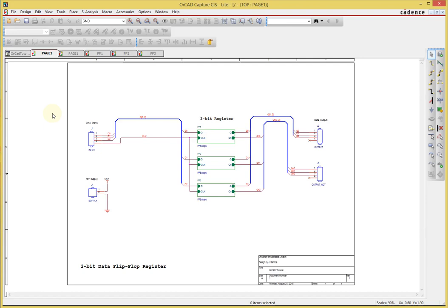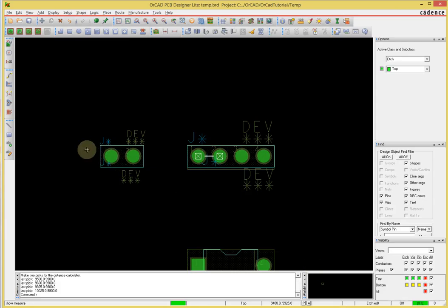Okay. Another thing I wanted to make clear is that there's nothing special about a footprint. It just says where the holes are going to be, what the hole sizes are, and there's certain information such as the solder mask and things like that. We're going to discuss that later. Even though this was called jumper, I can use the jumper footprint to connect any device that has a spacing of 100 mils and a hole diameter that fits this. I can use this pattern to just solder wires into it. I can stick wires into these holes if they are small enough.